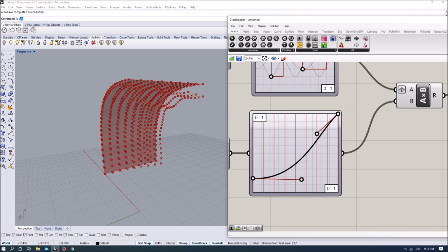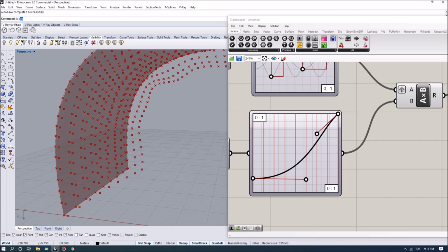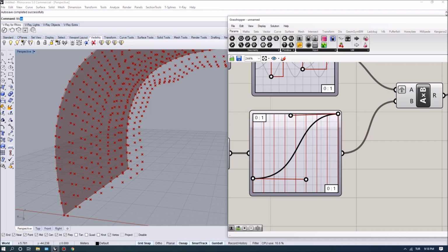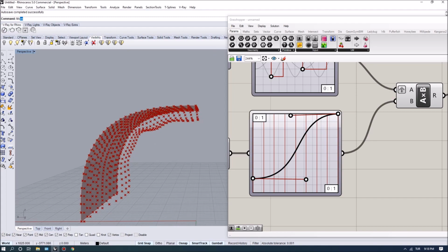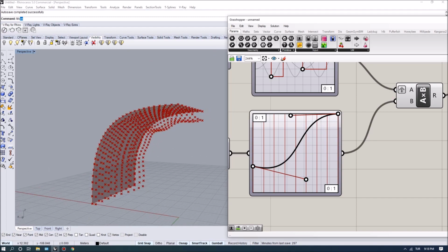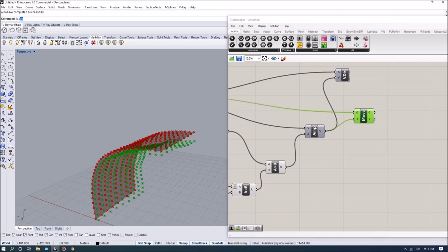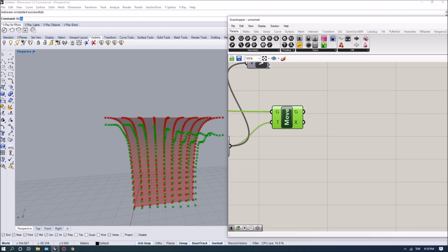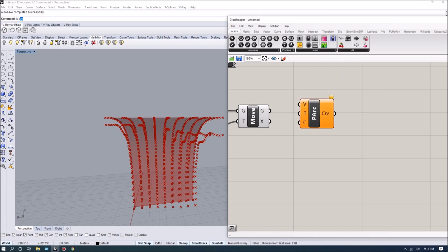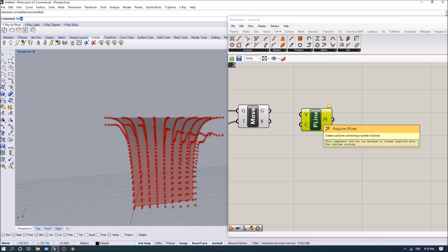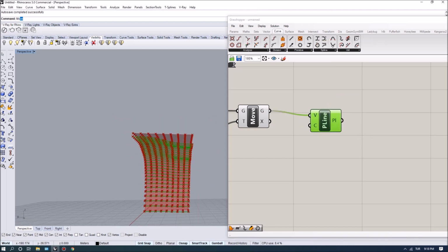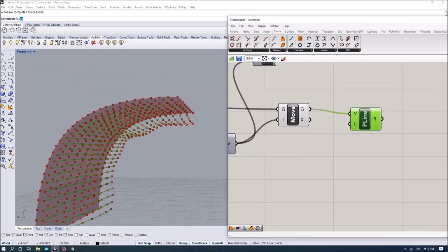So if I make it a Bezier, you can see that here the data is closer to the surface, because the initial values I'm feeding are small, whereas the later values are larger. So this will create the type of offset I want from the surface. This actually defines the end of the first point we want to arrive at, and I want to finalize this by turning each horizontal row into a polyline. So polyline, and you can find polyline under Curve, Spline, and each row will be turned into a polyline with this command.